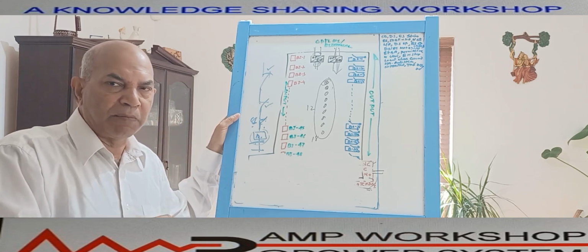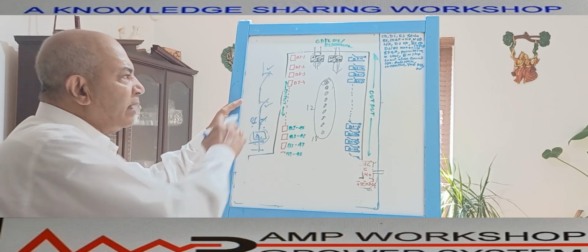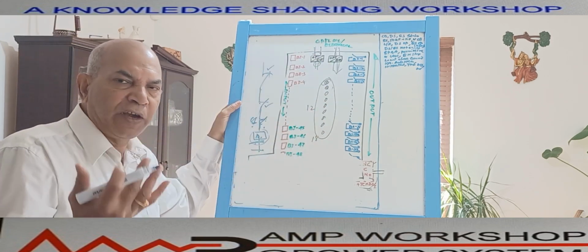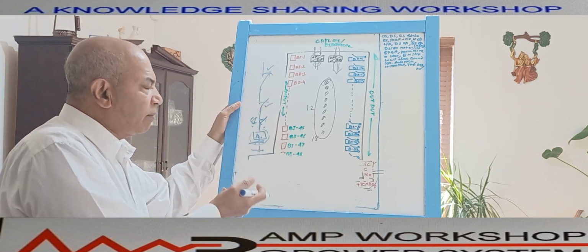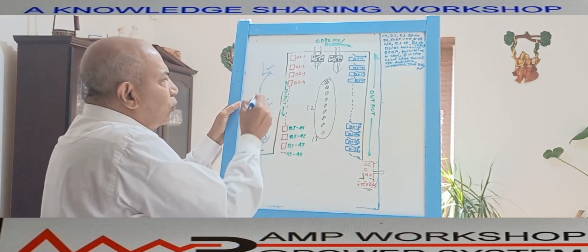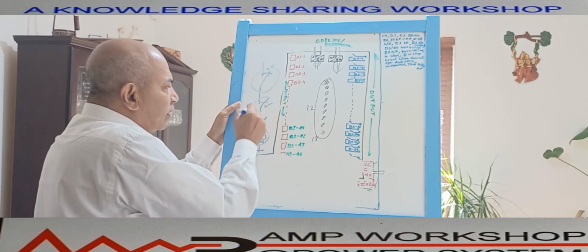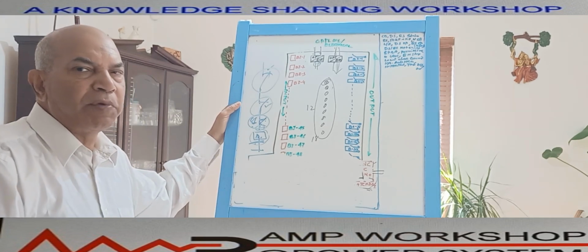We made that interlock in the old days, but nowadays all this interlock I can make inside the relay by configuration or by logic. To make this logic inside the relay, we need to know the conditions to be sensed by the relay. So all these conditions we have to bring to the relay.